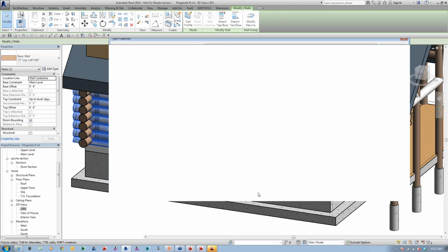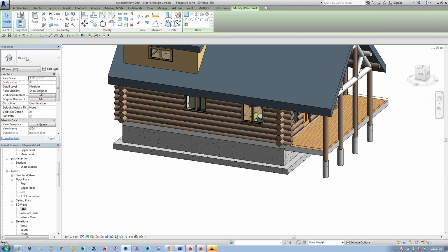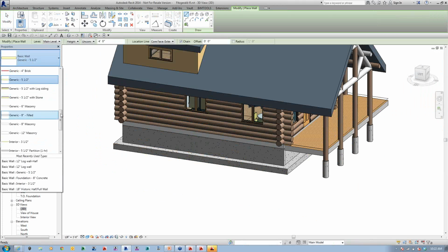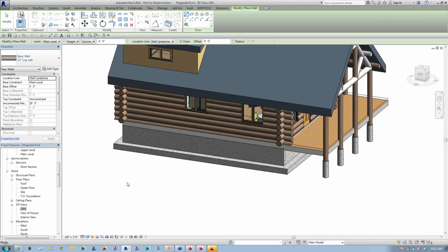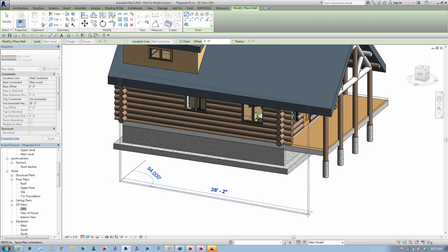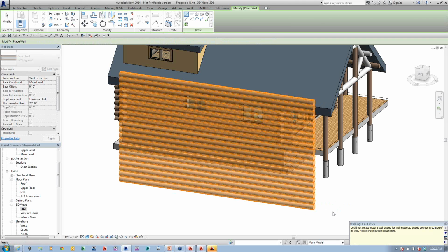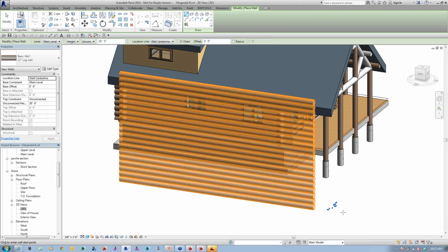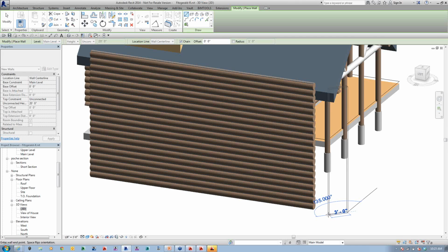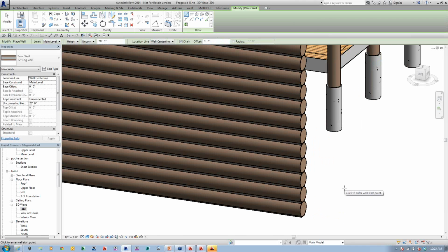Okay. So what's the end result? As I'm drawing these walls in here, I'll start off with my wall command, and then I'll go into the log wall. As I draw it, it looks like a regular wall. But when I hit enter, now I'm talking AutoCAD all of a sudden. When I finish the command and finish clicking, you can see I've got my log wall put together with my chinking in it. Okay, and I've got that all built up inside.